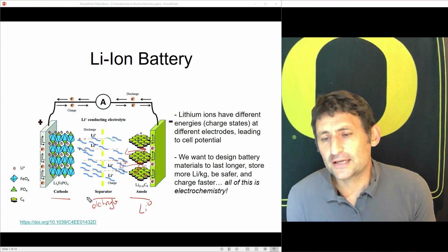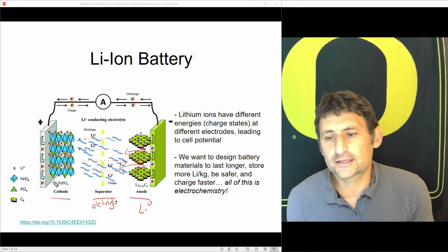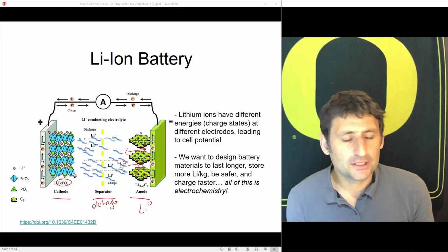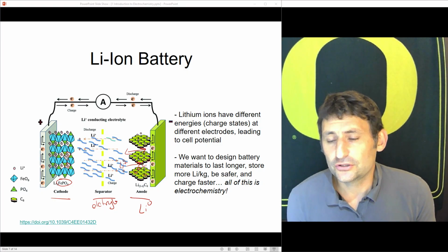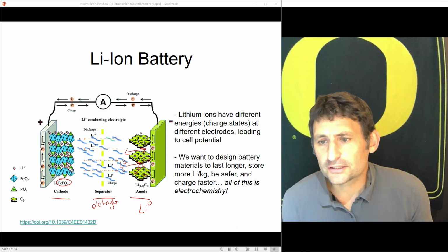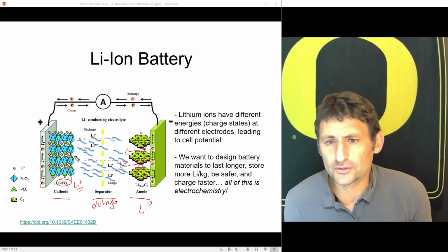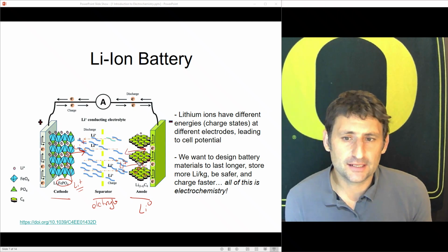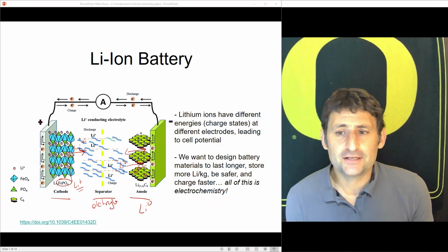And on the other side, the cathode, you have lithium sitting interstitially in an oxide. This is an iron phosphate cathode. There's a number, nickel cobalt oxide, variety of cathodes used. Those lithiums are essentially lithium plus, nominally lithium plus 1. Okay, so when you charge a battery, you pull lithium plus out of this side, and you put lithium plus in on this side. So you have lithium 0, and you have an empty spot over here left over. And to do that takes energy, right?